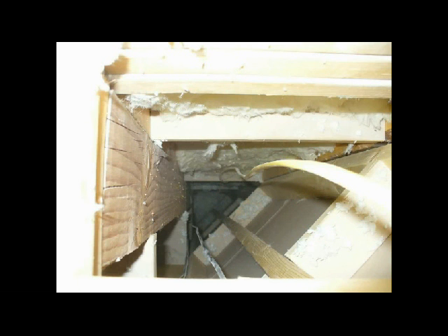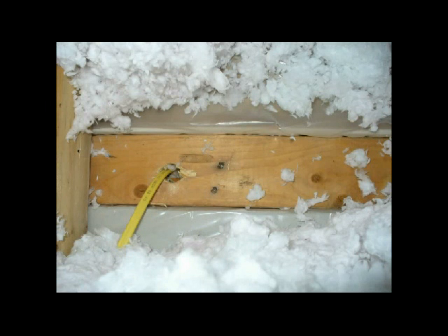But another one, real classic top plate air leak with an electrical penetration. As you move the insulation aside, you can see there's a pretty good size air leak. If this building was being depressurized, you could use your smoke puffer to puff down at it, and it would draw the smoke down into either the electrical penetration or at the sides of that top plate.